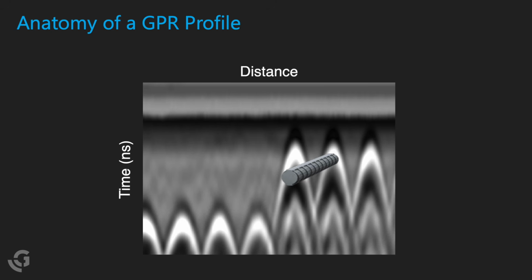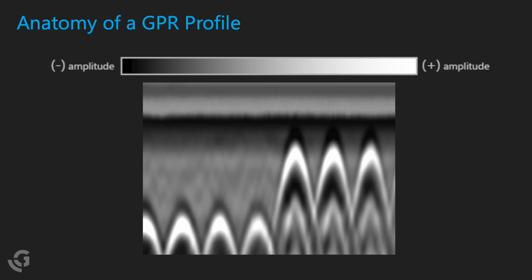Depth is calculated once we know the time it takes for the two-way travel time based on the properties of the subsurface. Time to depth is an approximation with a 10% margin of error. This will improve with more experience. It's also important to note that radar cannot calculate the size of the object in terms of diameter. Let's look at these hyperbola shapes.